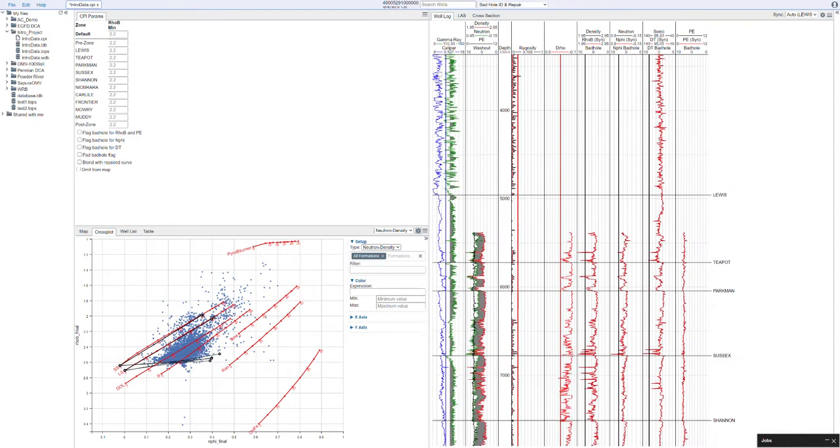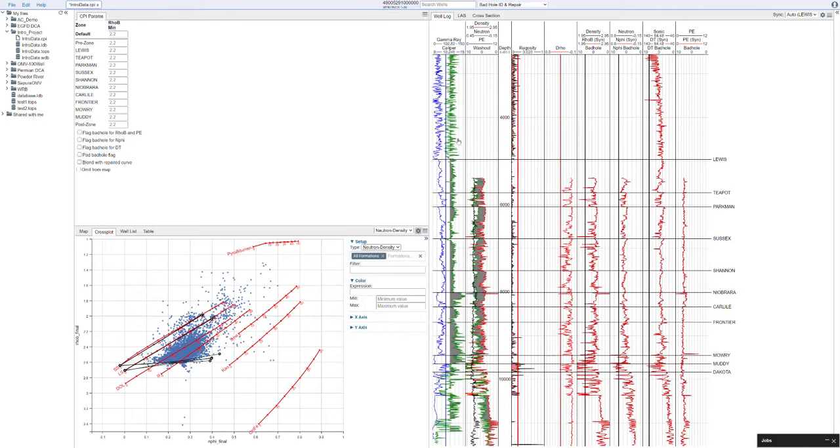I'm just going to zoom out here in this well, and what you'll see is that up here in the shallow part of the well, we have a caliper that's reading about 8 inches. The caliper is a mechanical measuring tool that tells us the diameter of the hole. So it's reading right about 8 inches, which means we're probably drilling this with an 8-inch bit. But we see quite a bit of noise in the caliper, and in some places the caliper value gets substantially higher. Here in this section we're generally varying between 8 and 9, maybe 8 and 10 inches.